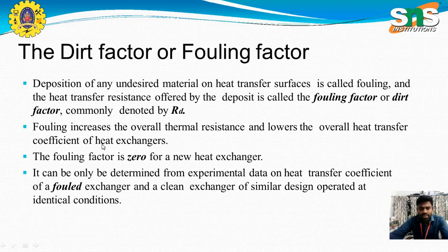And for a new heat exchanger, we don't see dirt or other unwanted particles on the surface. So for a new heat exchanger, we have the fouling factor as 0. It can only be determined from experimental data on the heat transfer coefficient of a fouled exchanger and a clean exchanger of similar design operated at identical conditions.